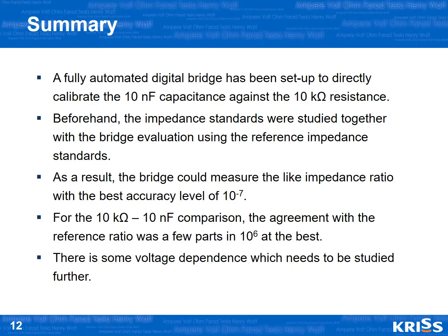Summary. A fully automated and reconfigurable digital bridge has been employed for tracing the 10 nanofarad capacitance from the DC quantum Hall resistance. Studies for the bridge measurability evaluation have been done mainly in the fully digital mode, together with exploring the basic properties of the impedance standards, such as the 1 kilo ohm, the AC-DC calculable resistor, the 10 kilo ohm resistor, and the 10 nanofarad capacitor.